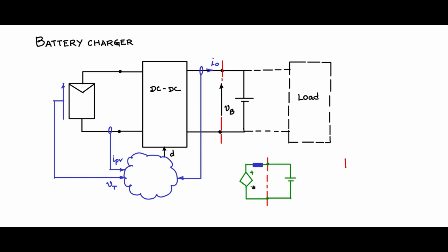So if you are having a controlled voltage source, have a series impedance. This is one possibility. But you don't want to control the voltage because the battery voltage is fixed. You can directly control the current. In fact, a controlled voltage source with a series impedance, and if the impedance is inductive, non-dissipative, that will form a controlled current source itself. So what can also be done is, across this boundary where you have the battery, you have a controlled source, and that controlled source you make as a controlled current source.